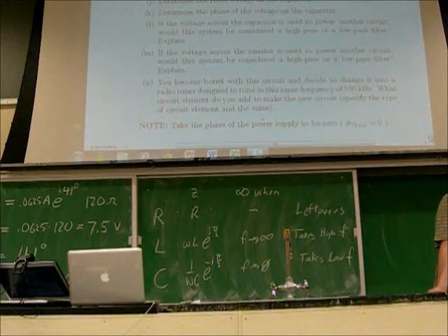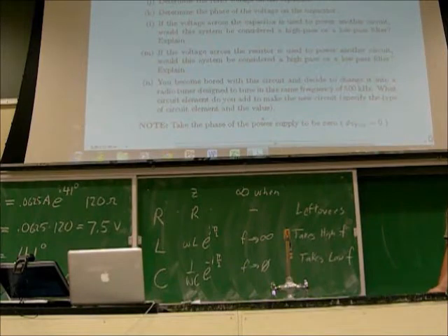Takes the lowest, and that the resonant frequency, at the resonant frequency, that's when you get the leftovers. So there's one frequency, the frequency such that omega L equals 1 over omega C, and that's what you get as the resistor in an RLC circuit, and that's why it's a tuning circuit. Because by changing the L and C, you can change which frequency goes to the resistor. And that's how a radio tuner works.